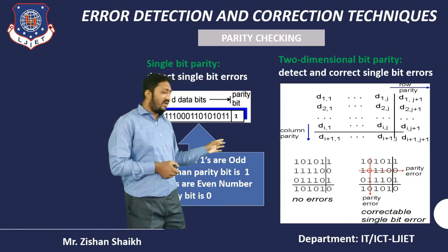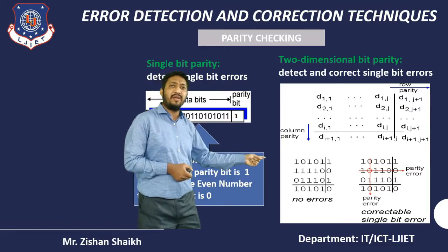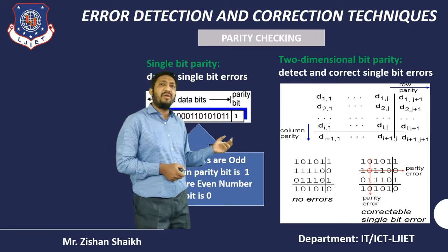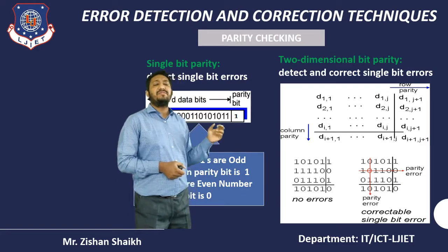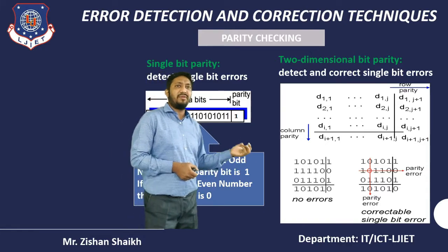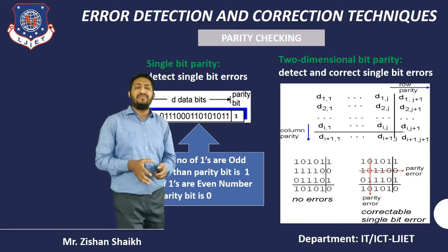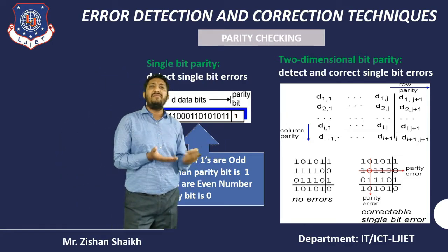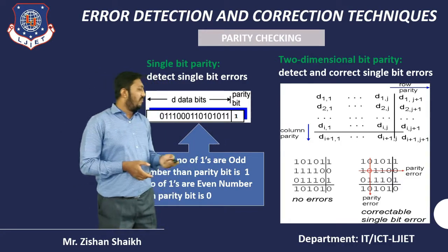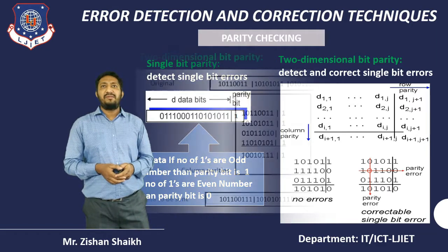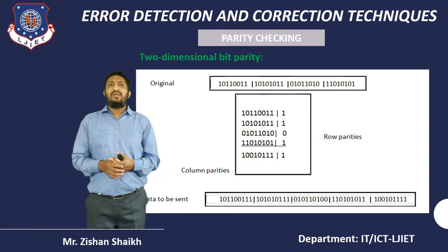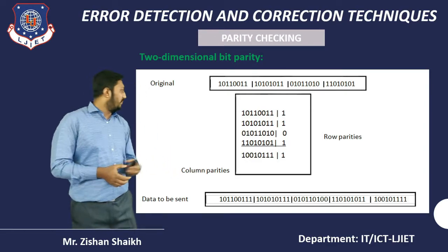So when we see in the first column and second column that the number of 1s is coming twice, it is an even number, and that is the case when our parity bit will be 0. Otherwise it will be 1. So column wise and row wise we have to check the parity bit. At the receiver side, if any bits are found wrong when checked, then we detect the errors. Now this is also another example of how we check the parity bit.